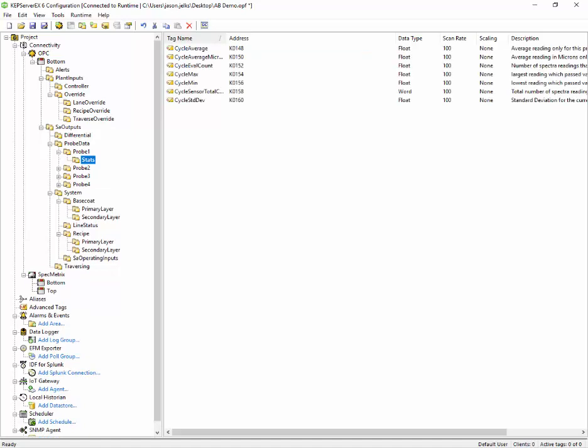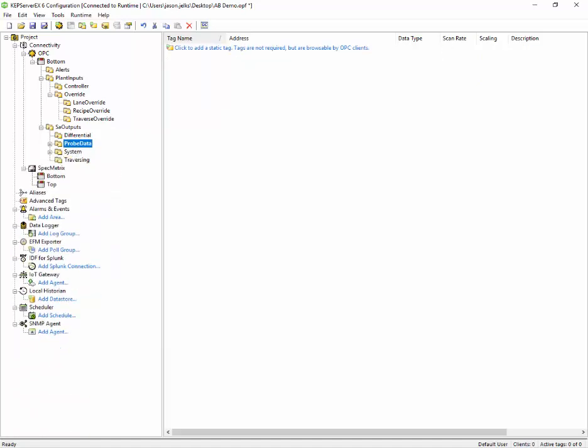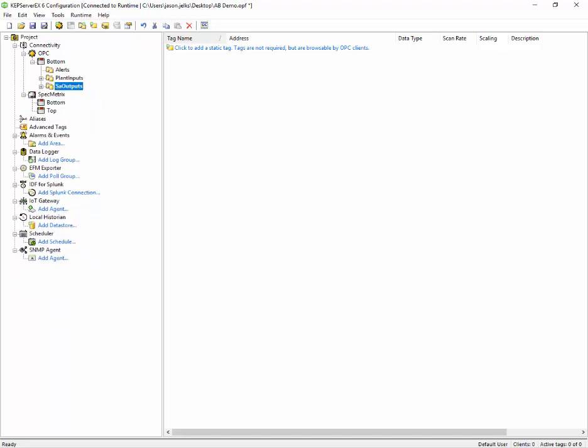And this is very easy when it comes to OPC. We can set these up on the fly immediately without having to have any actual physical device available. For PLCs, it is not as convenient. You actually have to have a PLC device, a proper one that is going to match up with the PLC device that is going out to a plant. We only have Allen Bradley as far as our setup controls for testing.